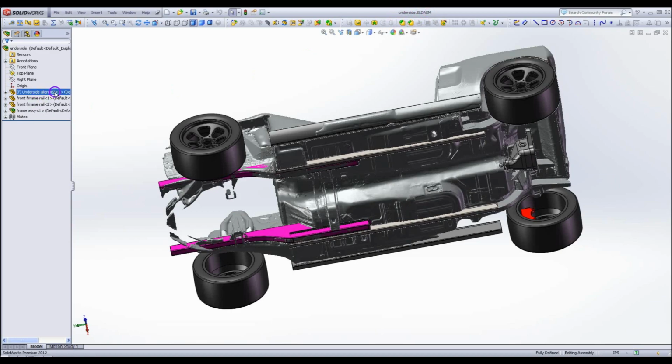This is my second version of aligning it. So, and that's fixed in space. And the problem that I had with the 3D scan STL file import is you can't move it. Once it's in there, it's in there. It's just fixed. No matter what you do, you can't move it. So I just made it into a solid assembly file, and then I import assemblies into that. And then I can move the frame assembly file relative to this and get it where it lines up.